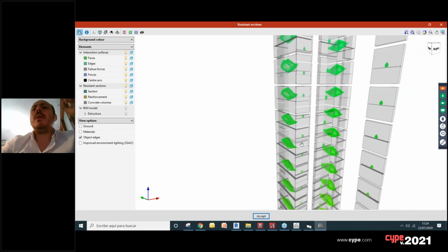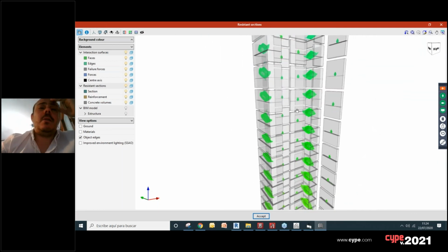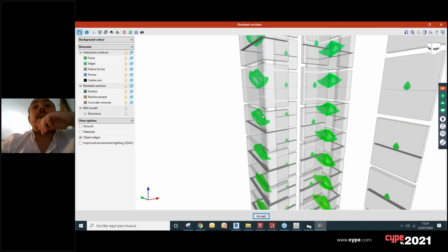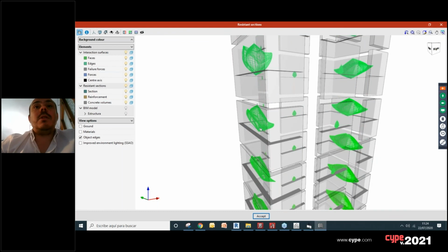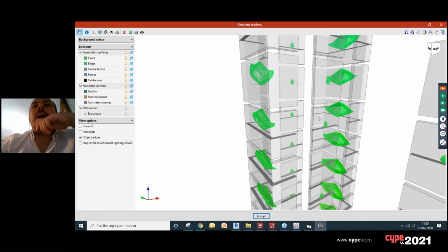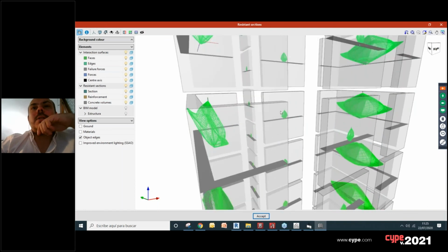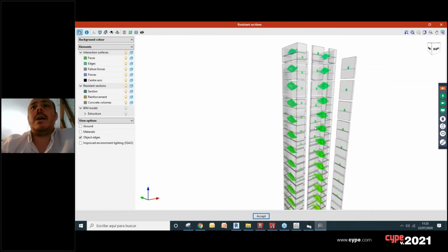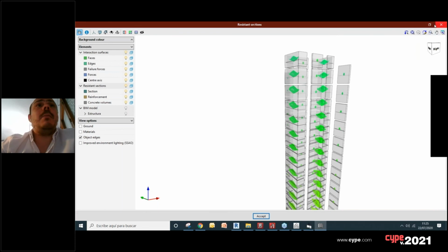What we see here is a result of the calculation of these shear walls. Actually not the rebars, I'm sorry, I was wrong. We must go to another software to see the rebars. But the coupling beams are used to connect two shear walls like here or maybe here. Almost always we do that above the doors, for example. It's a common place to add these coupling beams.